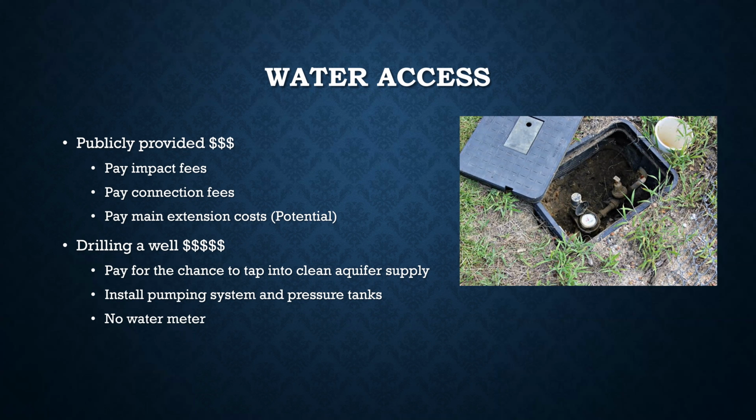Basically, you're going to get water on your site by either getting it as part of a public service that is part of a larger water sanitation company. It can be on a small level like an HOA, local water supplying, or it can be city provided, things like that. But basically, you're going to pay an impact fee. The impact fee is designed to cover the cost of the infrastructure of everything technically upstream of your water, not downstream, because that's sewer.